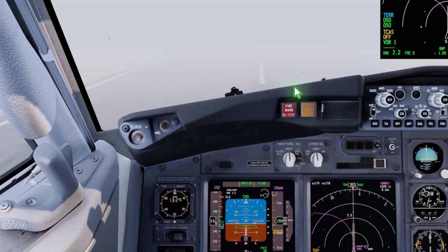So if you have a system that has automatic localizer tracking, it'll correct itself with the autopilot still engaged. But if it doesn't have localizer tracking, the autopilot will disengage, or you may have to disengage it, and then with your own rudder control, bring the aircraft nose to track down the center line of the runway.